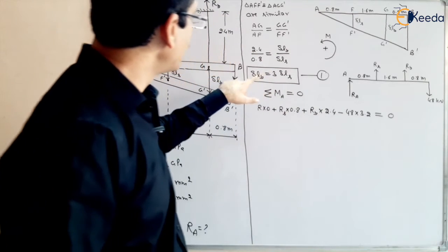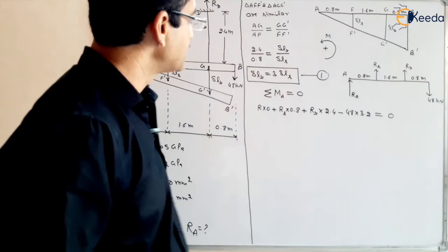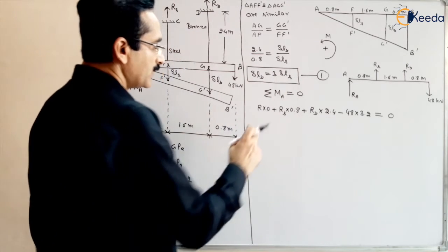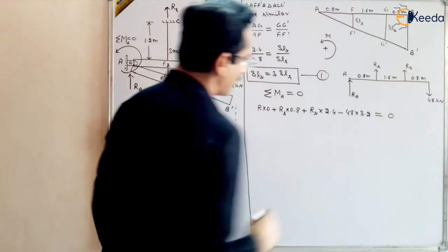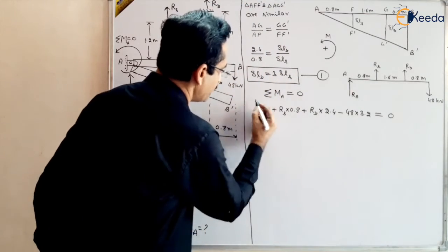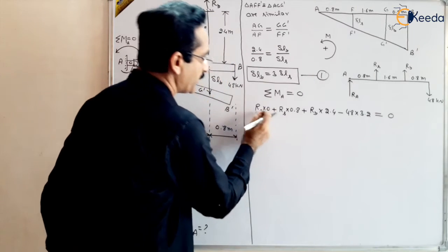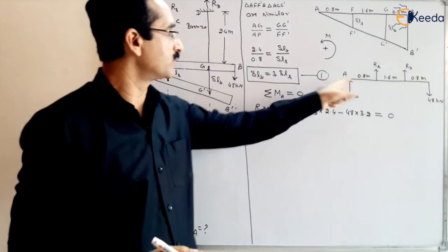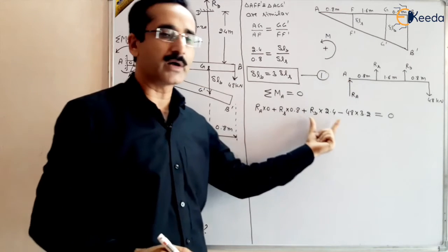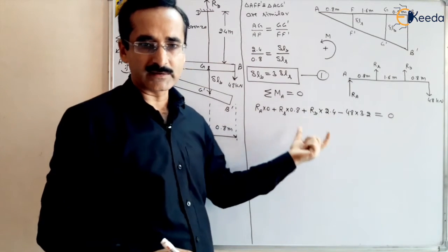The first relation we have already obtained, delta Lb is equal to delta Ls. So the second relation here we are getting. Ra will become 0 because it is multiplied by 0, there is no distance from A, it is acting at this point only. So there will be a relation between Rs and Rb. What is that relation? You can find out.